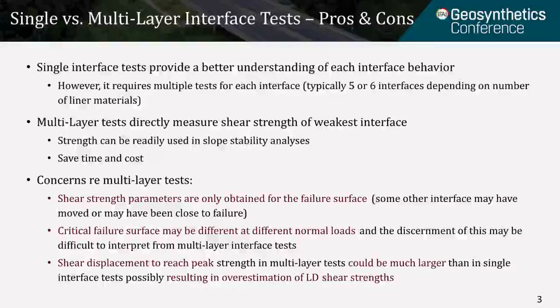analysis. It saves time and cost. There are still some concerns among practitioners regarding multi-layer tests, such as shear strength parameters are only obtained for the failure surface. Some other interface may have moved or may have been close to failure. Critical failure surface may be different at different normal loads, and the discernment of this may be difficult to interpret from multi-layer interface tests.